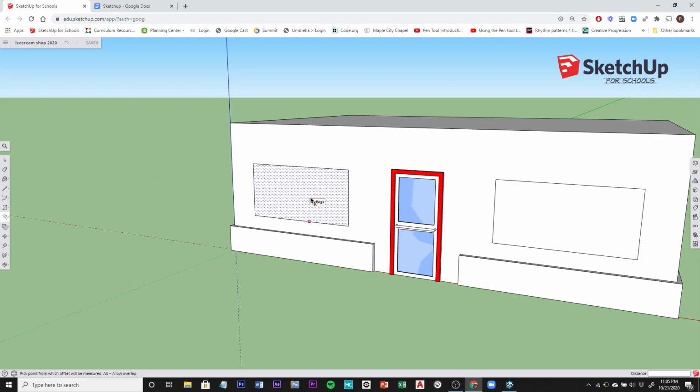So in this one, you want to click on the inside of the boundary that you want to offset. In this situation, we want to click on the inside of this rectangle. Don't worry about the screen tip where it says on edge. That just means this is the edge that we're going to be offsetting. So we're going to click on the center. And now, so it's just a one click and release. Now you get an adjustable offset. So on the inside I could offset, or on the outside I could offset. We're going to make an inside offset